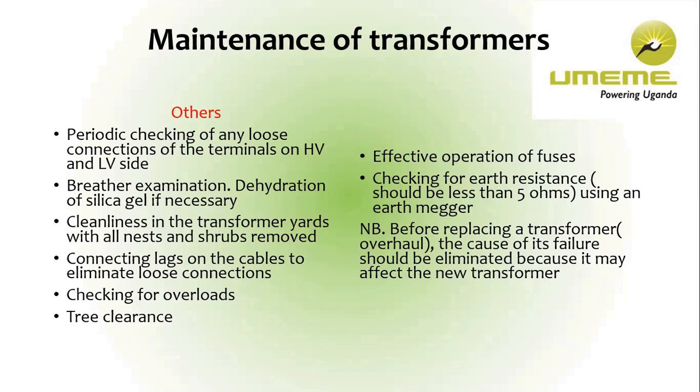To the south there is 50 current. To the east we have only 10 currents, 10 amperes. When I talk of currents, I am talking about amperes. East 10, and then west we find only 3. That is not a balanced load. You have to make sure that that transformer is extended more to the 50 ampere zone.